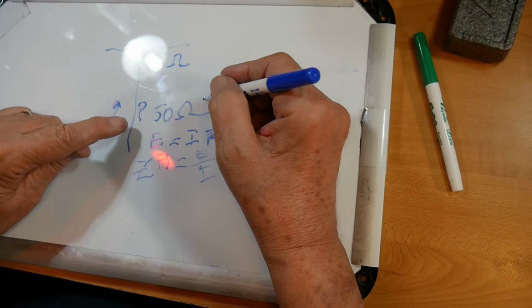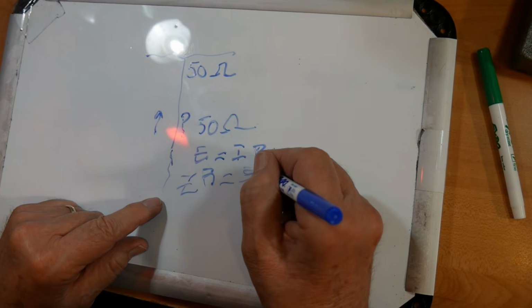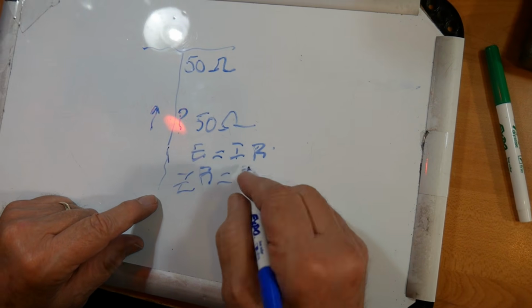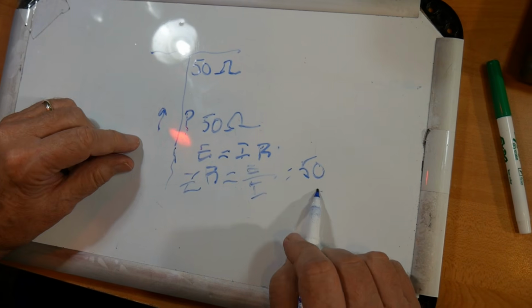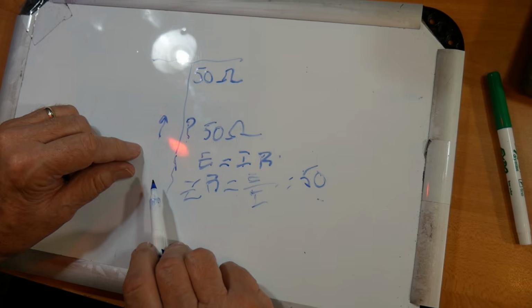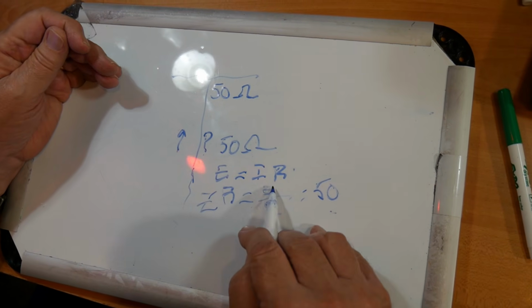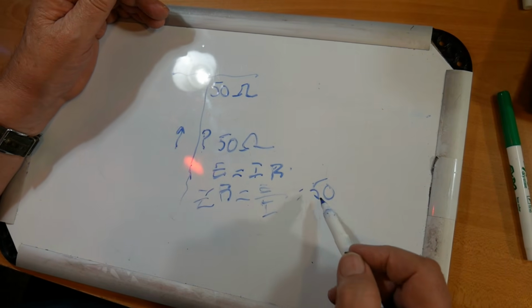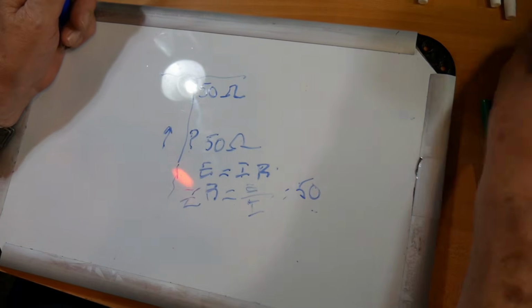Okay, we call this 50 ohm cable because everywhere along this at RF, the RF current divided into the RF voltage, the ratio of the voltage to the current, is 50. So if you got 1 amp of current, you got 50 volts. All right, ratio of the voltage to the current. Now, we generally like to transmit more or less power than that. Okay, it's 50 ohms. Now, I want you to think of something funny.